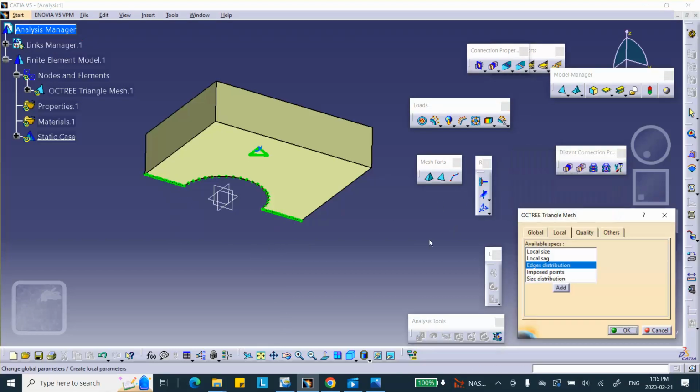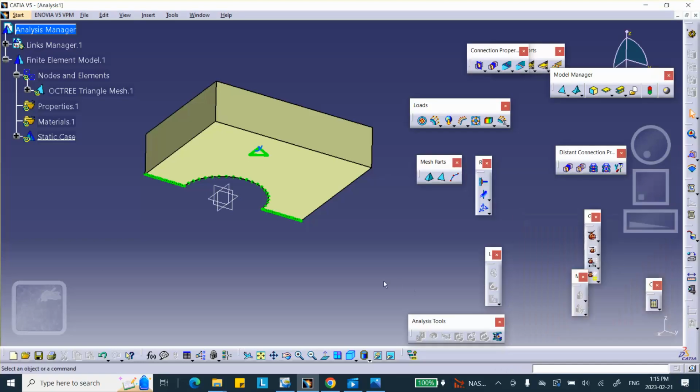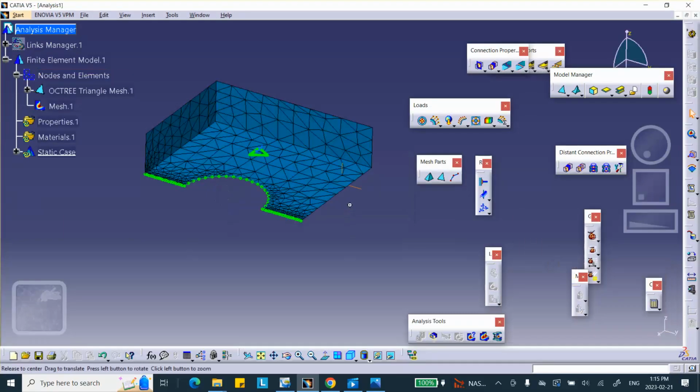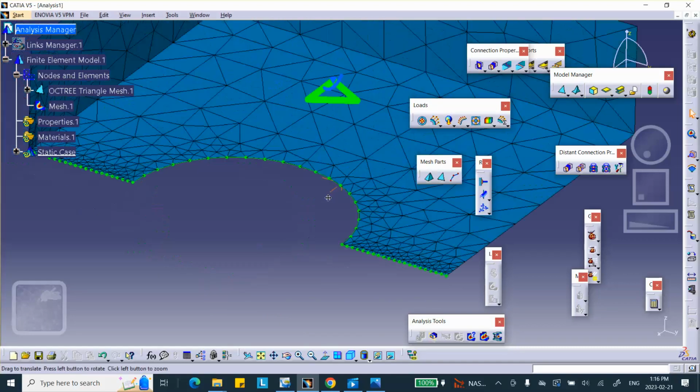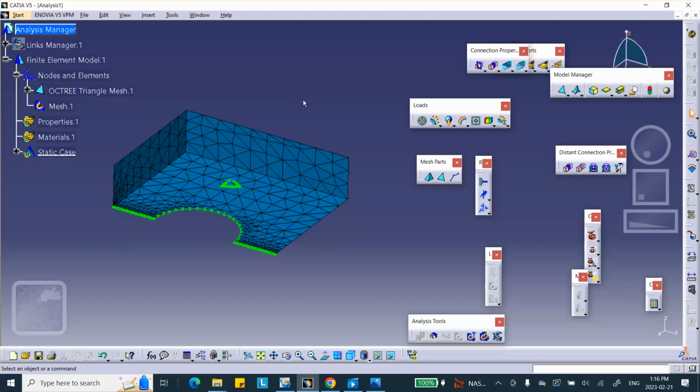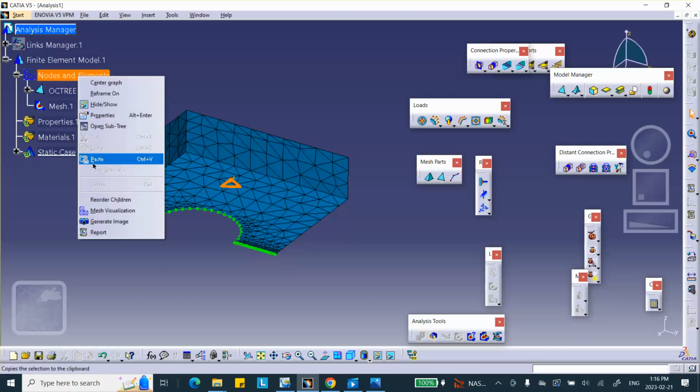That's not needed really, but okay. And if you look at the mesh now, you see there's a fine mesh around these things. Unless I'm asking you to do it on the test, please don't use local mesh refinement. That's unnecessary.